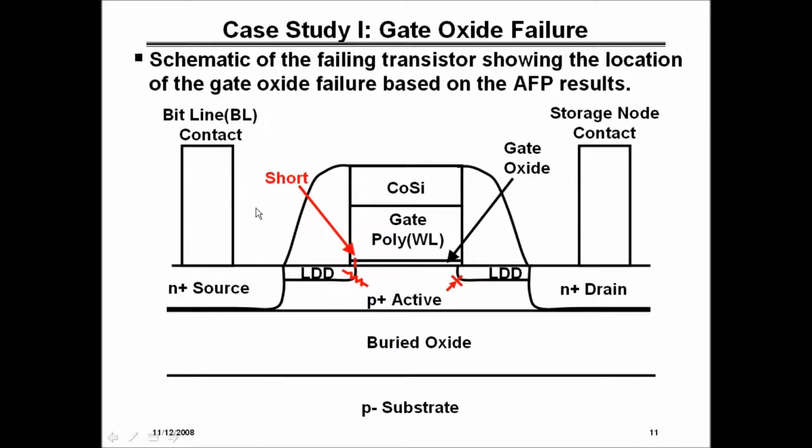And in fact, for the most part, when we identify gate oxide failures, typically our manufacturing people accept our electrical characterization results now based on these past experiences. We still attempt a physical analysis to try to identify it. In some cases we can, but more often than not for sub-100 nanometer technologies, we never see anything with gate oxide failures.